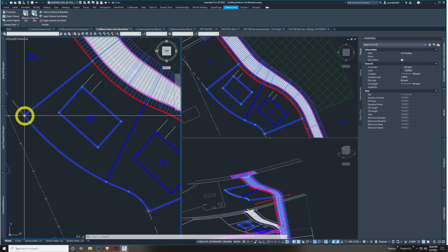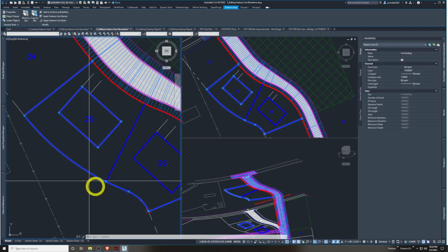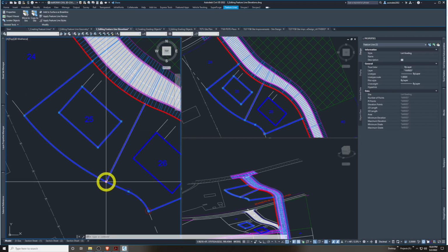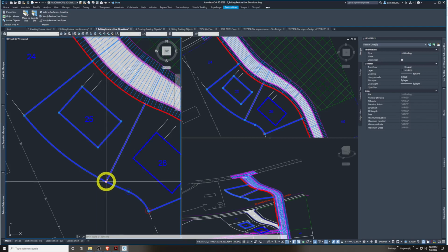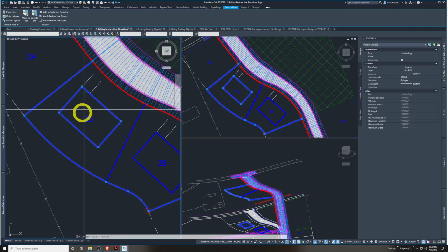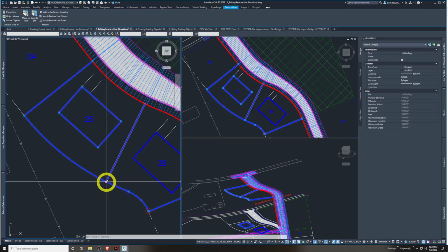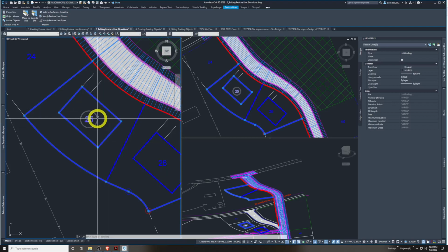So we had our lot corner over here, which was, this one was at 190 and some change. This building pad, actually this one was a little higher, 190.45, as you saw here in the coordinates. So this building pad might be just a bit higher than its highest corner, okay? So it's the highest point. That might be one starting point you would go to and then go from there.